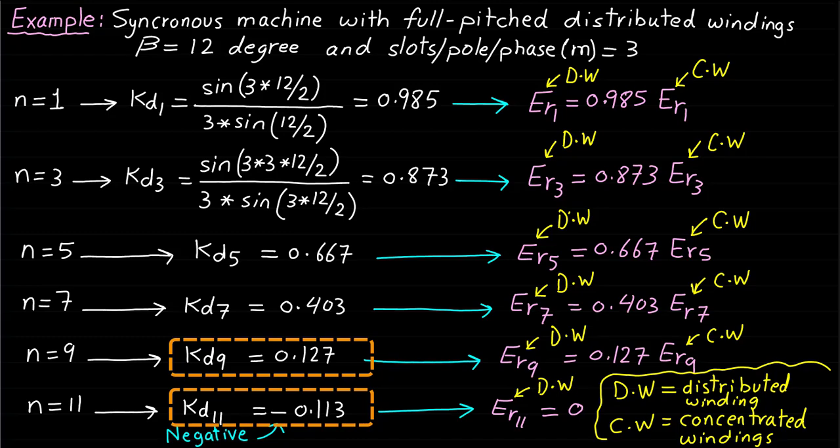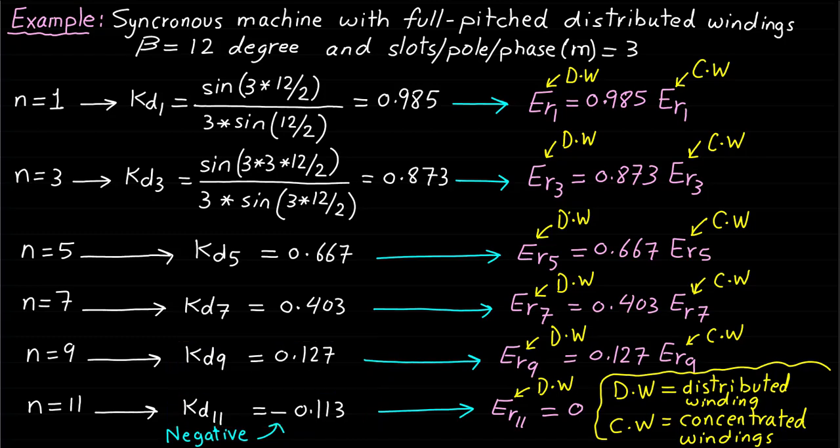Note that using good rotor design also can reduce the high-order harmonic components of the induced back EMF voltage, as we discussed in previous lectures. At this point, we should know that a proper rotor design and a proper armature distributed windings design are both contributing in eliminating or reducing the high-order harmonics.